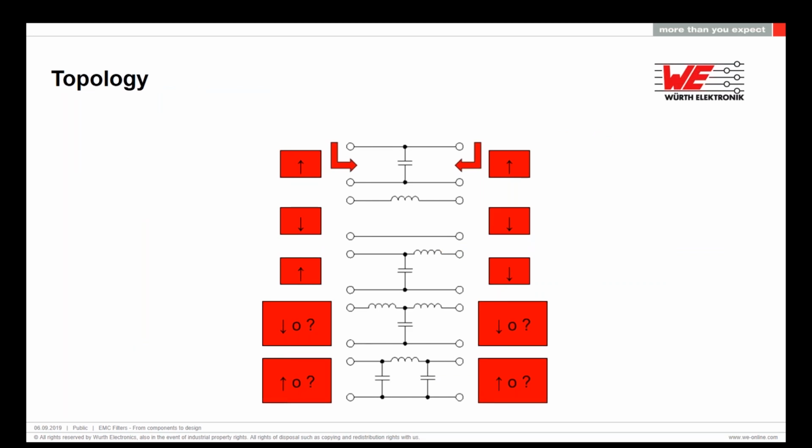Once we talk about the components we have, something we have to consider is that the placement of the components is also really important and relevant for our filter and the efficiency we will see in it. In this case, we have different orders of filters, from order 1 to order 3, which means we have 1 to 3 reactive components. And depending on whether we have a high impedance or a low impedance in the line, we will increase the efficiency of our filter by starting with a low impedance, which would be a capacitor, or starting with a high impedance, which means an inductor.